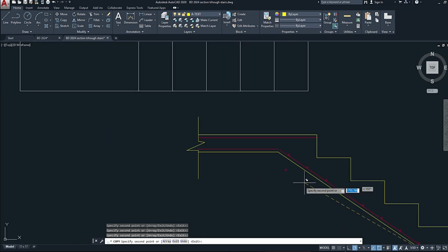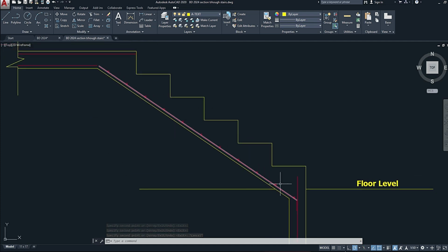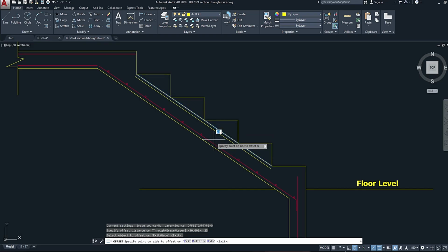Now, depending on the type of builder or engineer you are, you might leave this as is. But some engineers or designers will do this a bit differently. So similar to a roof slab, you'll have over support as well, and that is what this one here is. So I'm going to repeat the process of drawing a line across the base, like this, and then offset that line by the 25, because that is the cover. Then you can erase that line, no further use.